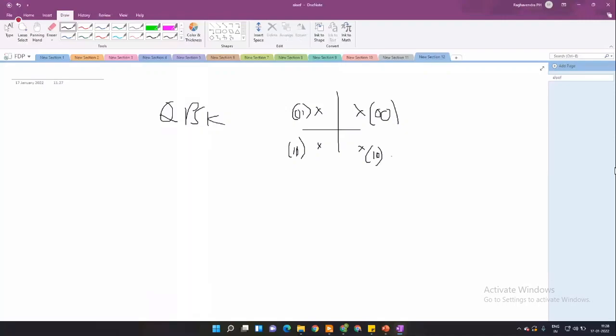What happens is, if I receive a stream of 1 0, 0 0, and then 1 1, I'm actually supposed to convert it to these QPSK symbols, and the actual I and Q values of these would be 0.707 plus j 0.707, and then for this it will be minus plus, for this it will be minus minus, and for this it will be plus plus. When I say modulation, I am simply converting these bits into these symbol values.